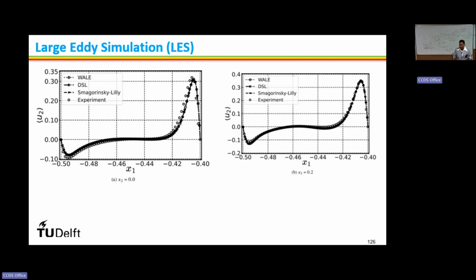Based upon the geometry, if there is some source or something happening in a particular region, suppose flow across a cylinder, throughout the wake region, why do you need a fine mesh? You need it where the flow reversal or vortex shedding is occurring. In the free stream region, we don't need such a fine mesh. You need to capture the vortex shedding just in the wake region, right?